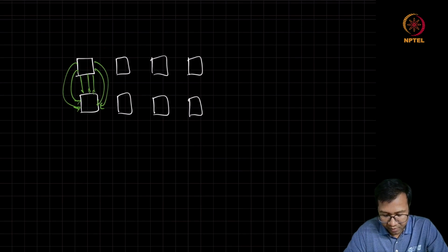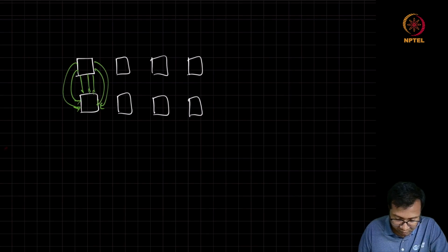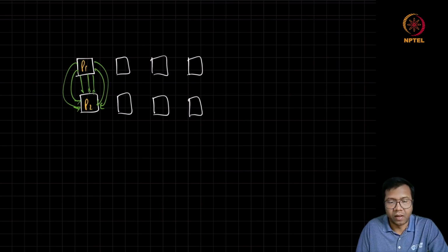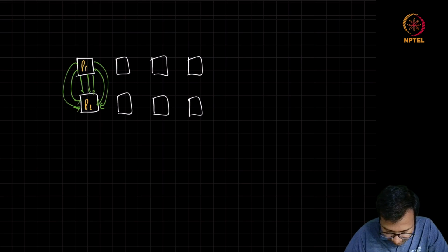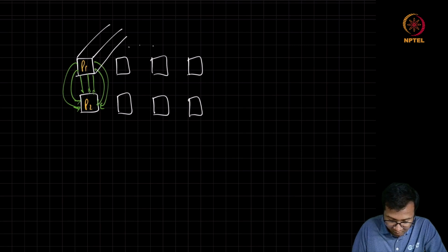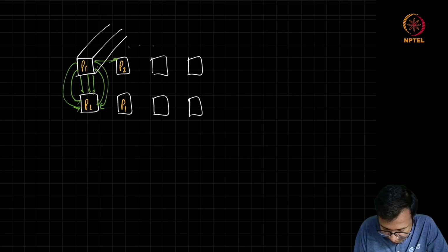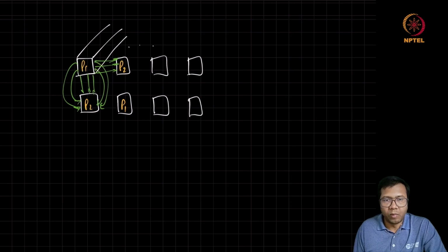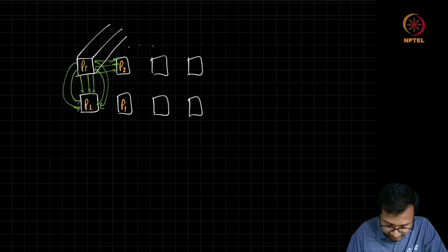And to further improve the capacitive density, what we can do is, if we are choosing this as, let's say, P1 and this as P2, the neighboring strip we can choose to be P2, and then here we can choose P1. So now this is going to increase the overall cap density which we can achieve. Similarly, P1 and P2.